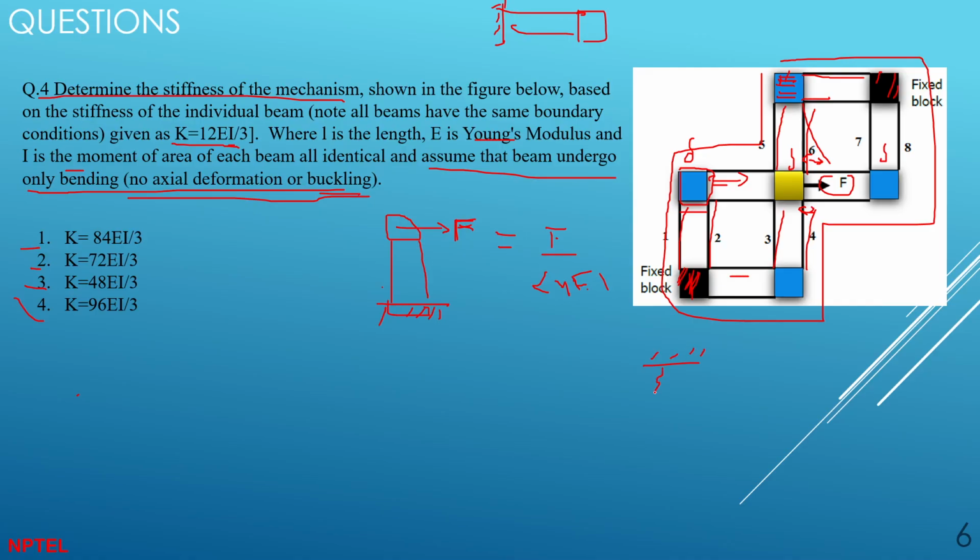If you remember from your elementary level, there is something called a series and parallel problem, right? If you have two springs connected in series, which have K1 and K2, the force remains the same, but the deflection will be delta 1 plus delta 2. Here you've seen something like K1 K2 by K1 plus K2. So this is what the effective stiffness of the spring will look like.